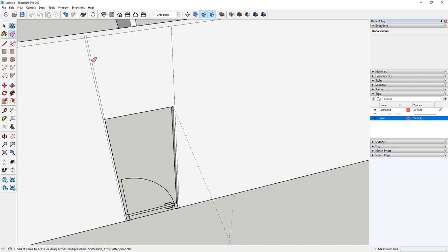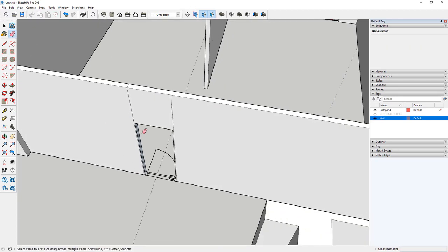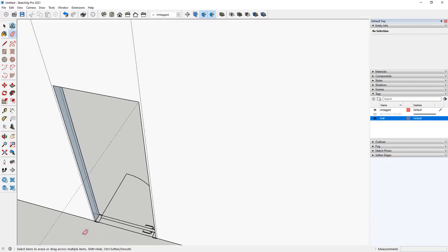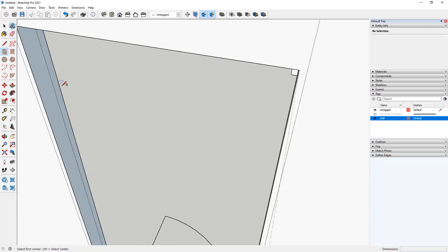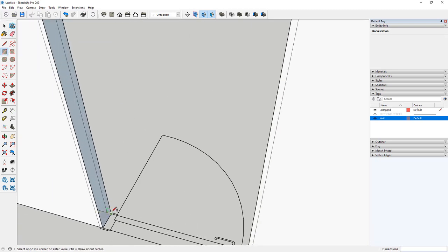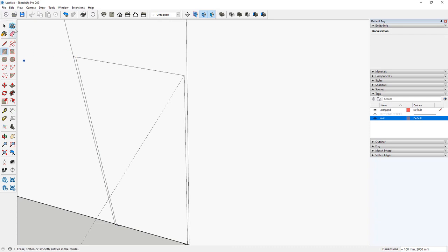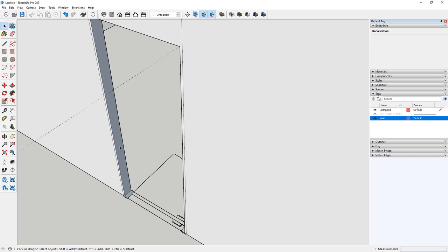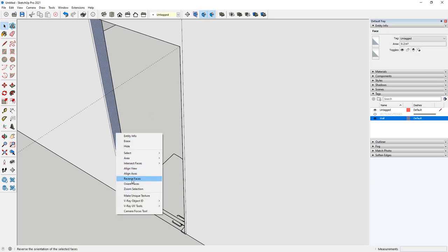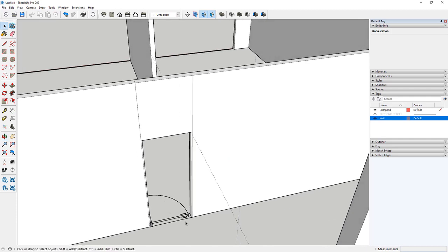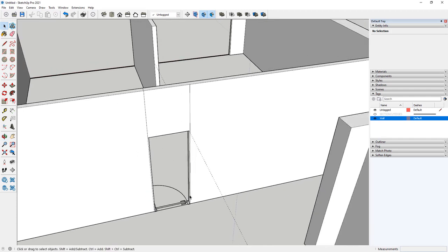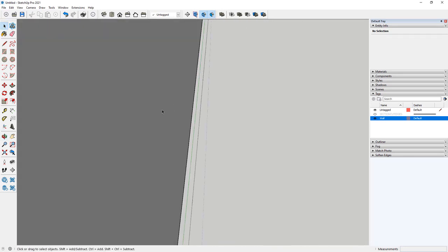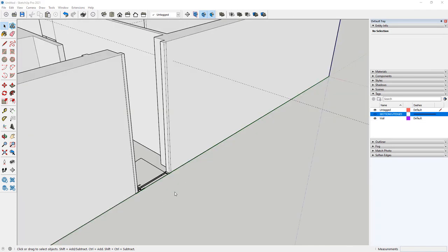Then we'll use the erase tool to remove unused lines, and sometimes this could be annoying because it will generate more gaps. So for example, in this situation we can use a simple surface. Then we need to remove both additional surfaces, and we need to also reverse the side for those inside. Okay, and we have the place to add the doors, and the same we will add for the entrance.